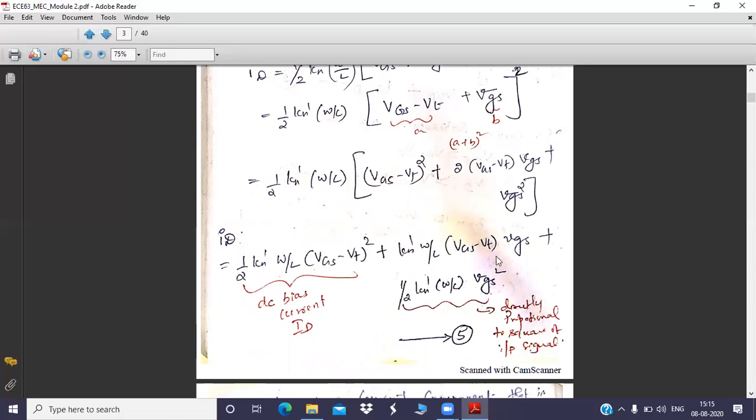Now, yes sir. From this, when you see this term, it is full of capital. You don't bother about this and all. Okay, this will always be there. You just concentrate on the voltage term. These are DC. This is DC. Always a threshold voltage is DC only. Please keep it in mind. The threshold voltage will be DC only. So this is going to be DC current, so that will be capital ID. I have shown here capital ID because this is pure DC.